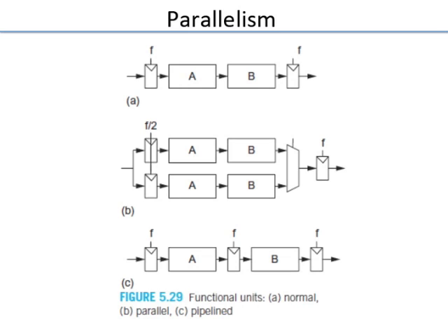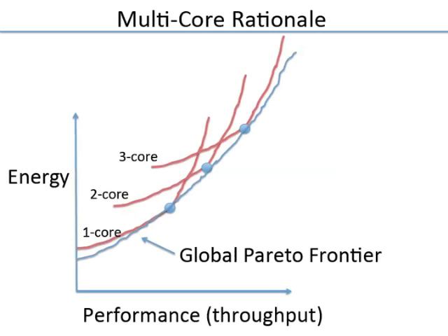At the end of the day, there is a certain throughput required, and you want to guarantee it. Let me come back to the encryption engine. So many encryptions per second you need to do, so there is a certain required throughput. I can either do it using a single engine running at that frequency, or I can have 2 of them running at half the frequency, and so on. While doing that, I'm making sure the throughput is kept. But now I'm comparing which is better from a power perspective, and it really depends on the throughput value.